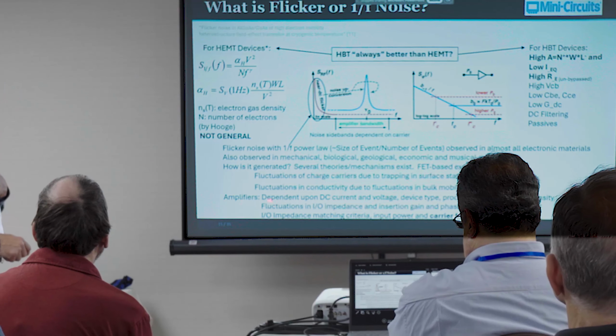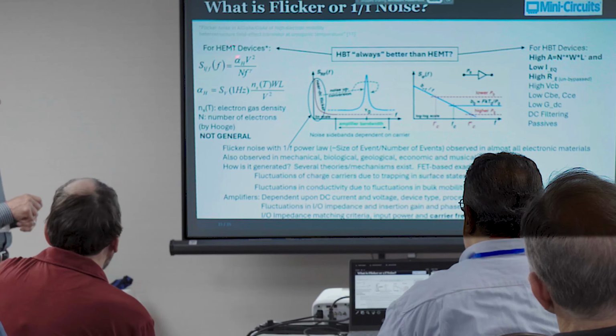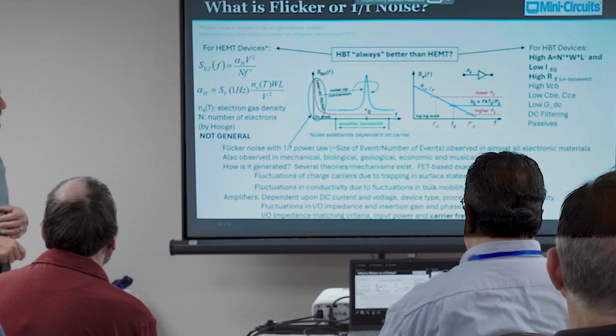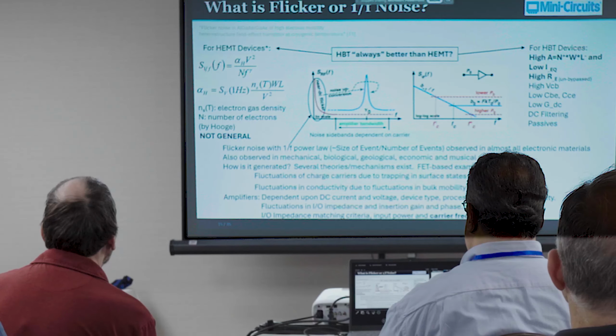What we can say with pretty much certainty, it is dependent upon DC current, voltage, the device type. Is it a PHEMT? Is it an HBT? Process node size, well, what's the gate length? What's the emitter width? All right, those all affect things.